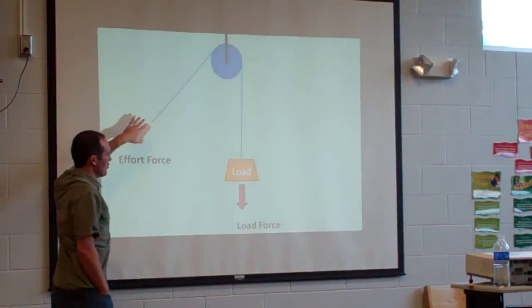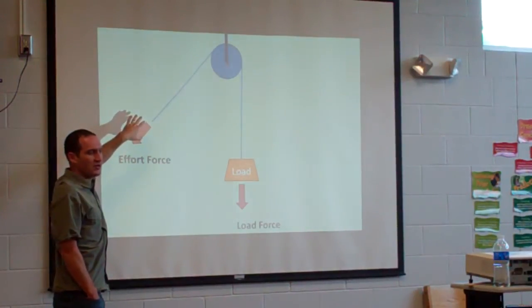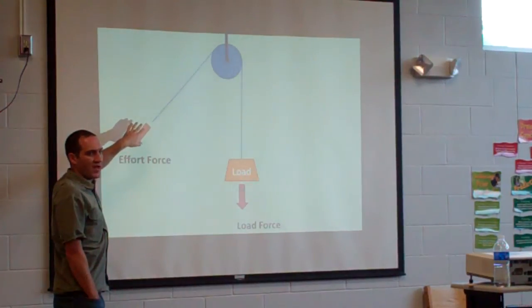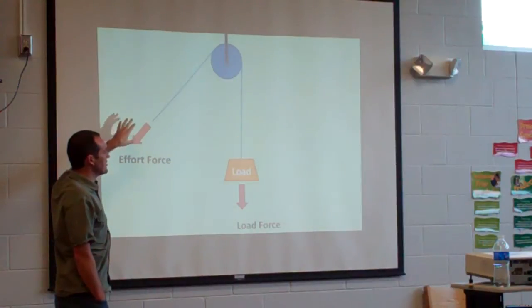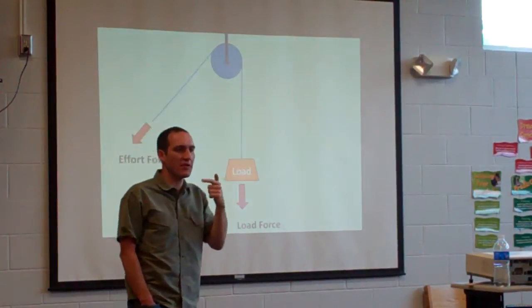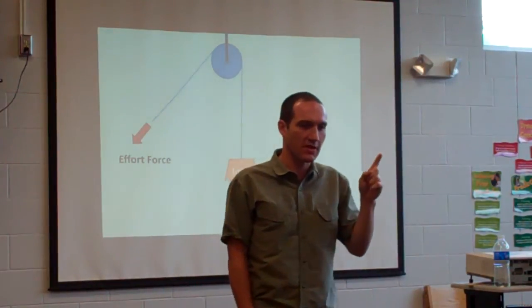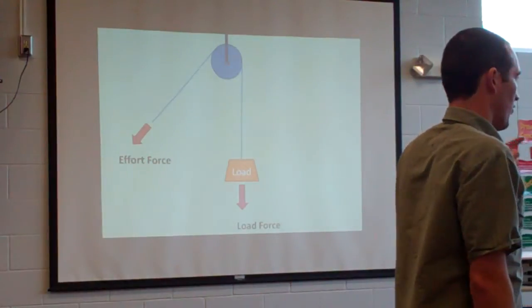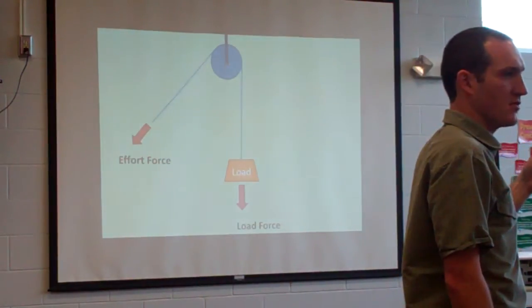This machine I've just shown you here, do you think there's any mechanical advantage? Are we getting mechanical advantage of more than one here? No. This pulley's not really amplifying force. It is doing something interesting though. It is a machine that's doing something helpful. It's redirecting force.